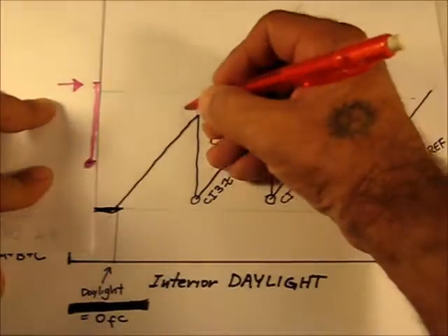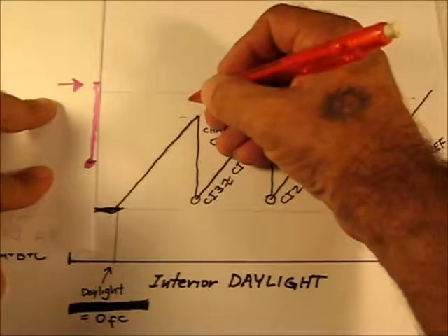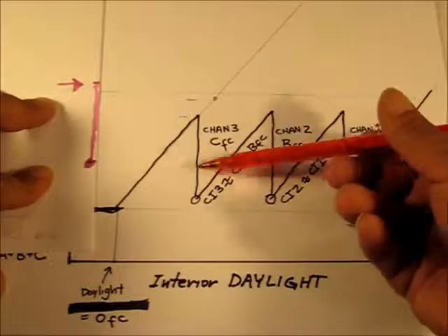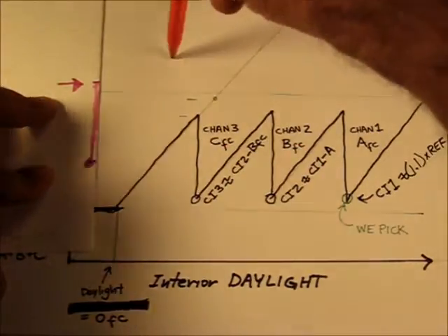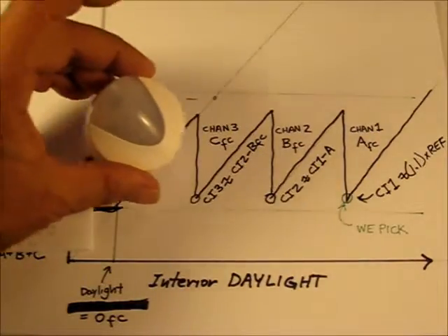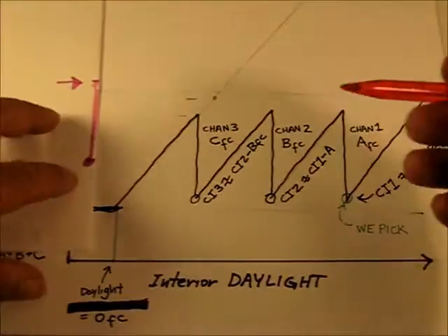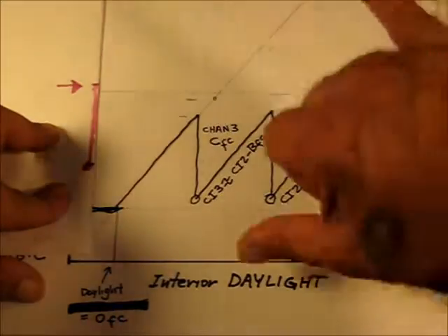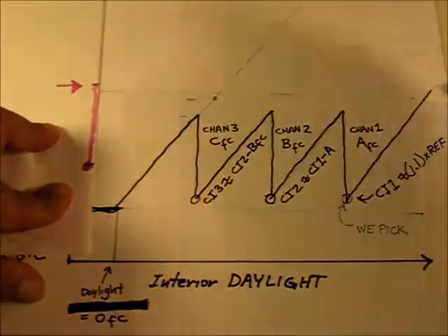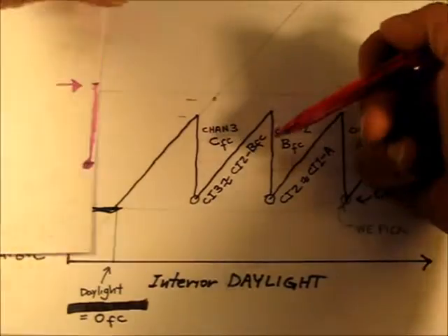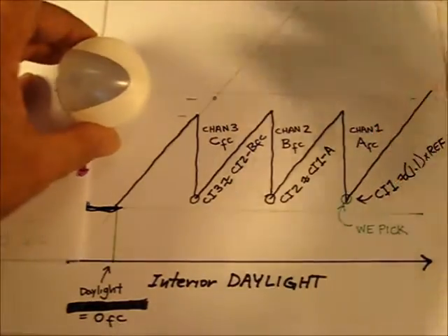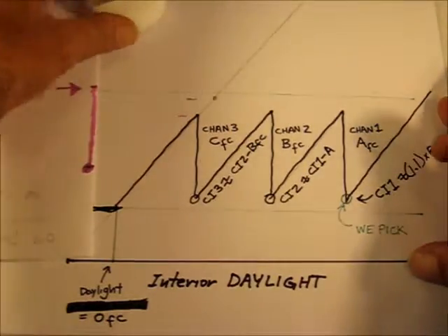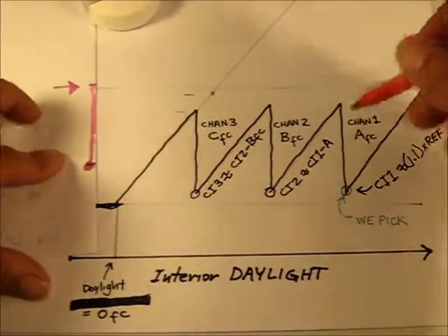This has got to equal, actually exceed, the amount of controlled lighting from this stage that is getting to the system sensor, right? Because if you don't have this deadband in here, system's going to cycle on and off and on and off. So our minimum deadband value is based on what we guess or have measured is going to get to the sensor from each of these stages of controlled lights.